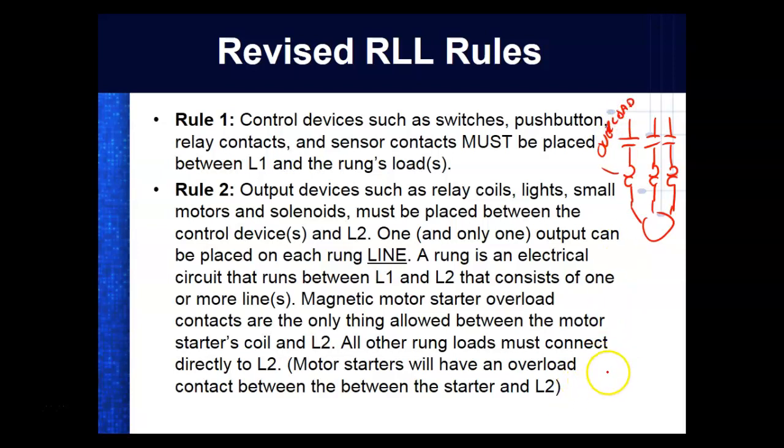And then in our control circuit, if I was to come over here and redraw that control circuit that allows me to start, stop, and seal in, over here I might call this M1, a motor starter. And then right here we'd put a set of contacts. That's the overloads, and this right here would be L2. So these are the actual overloads themselves. Overload switch, I guess you call it.